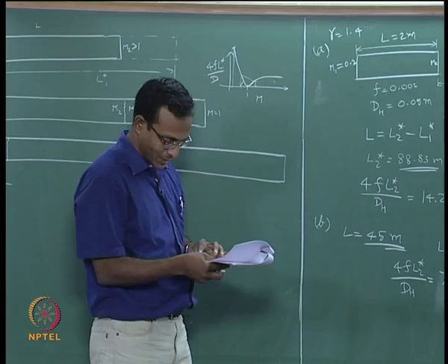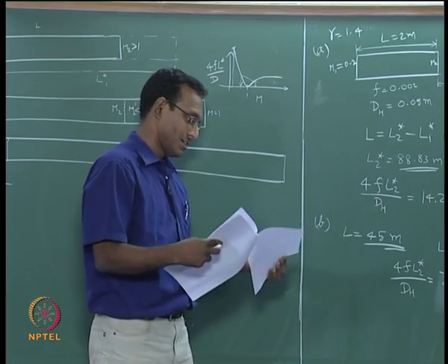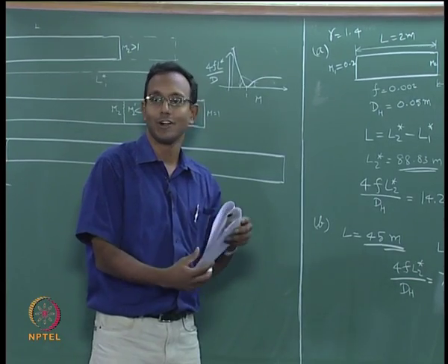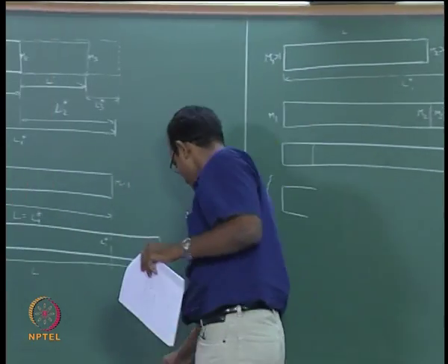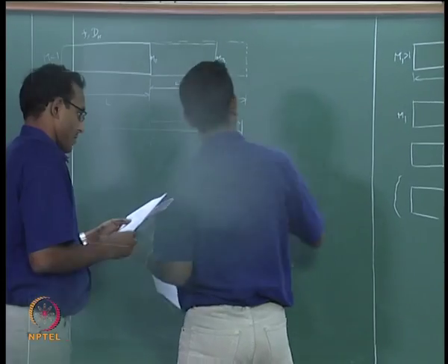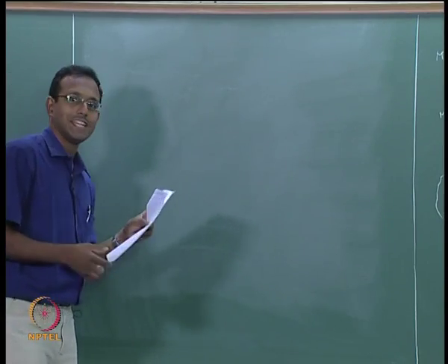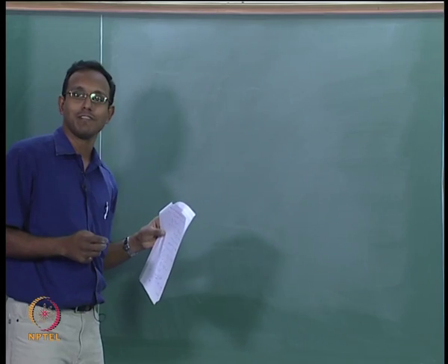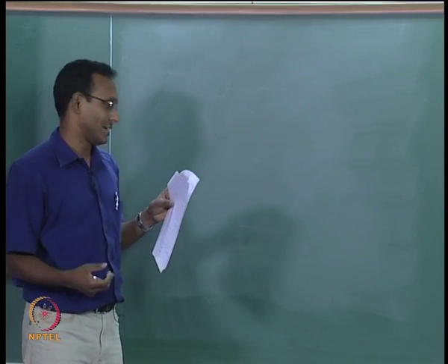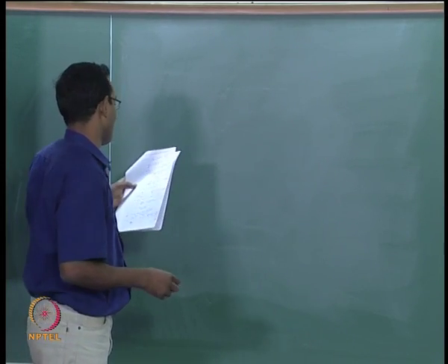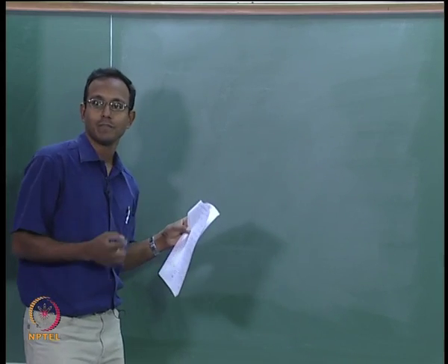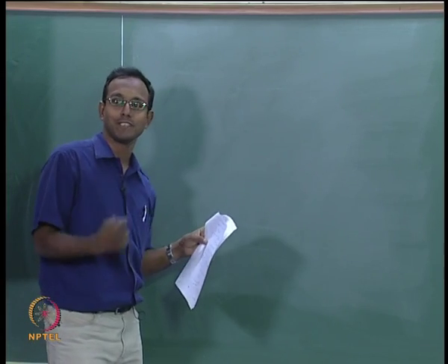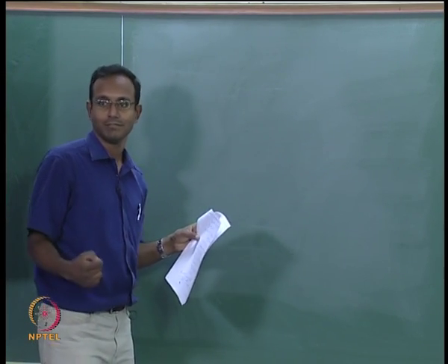Okay. So, when you get an answer like this, you should think about whether it is ridiculous or not. Currently it is not. So, you can live with this particular problem. Okay. Now, I will change the problem in another way. I do not want to solve it in Mach number domain. Suddenly I want to solve the problem by saying how much length should I have so that my pressure at the exit is half of pressure at the inlet. Okay, I am changing the problem.